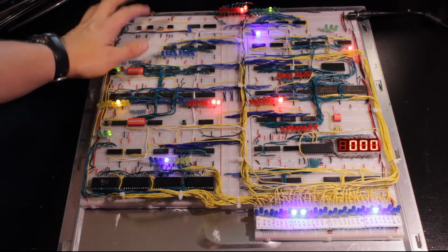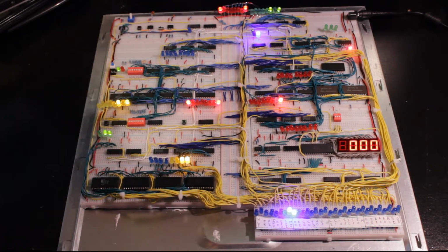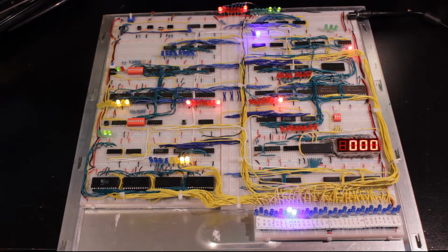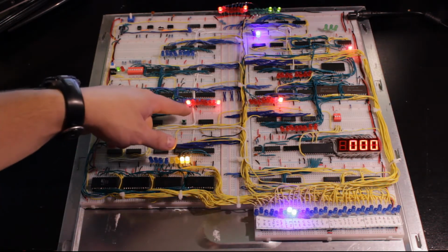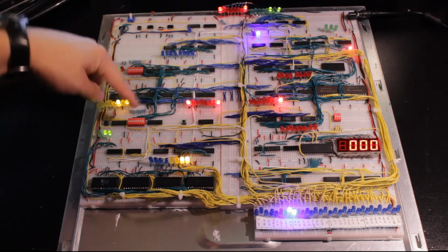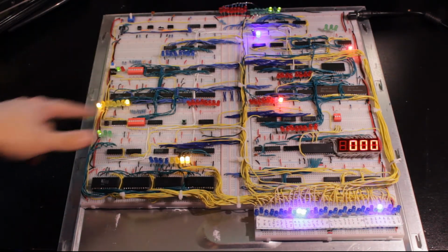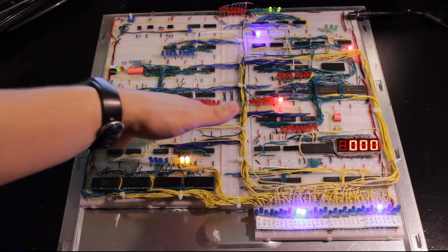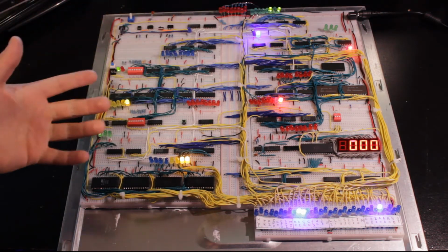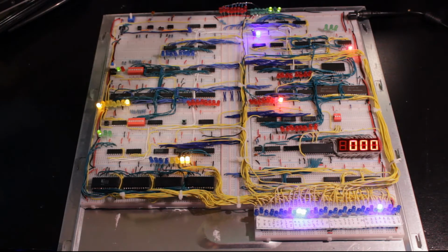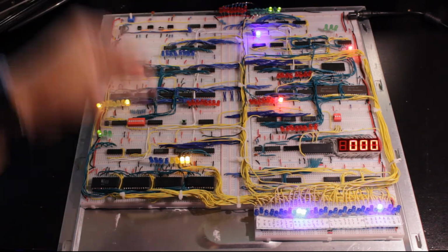which, as we said previously, is going to get a pointer to the location in memory where it's going to store the value held in the A register. So we get that pointer, 0x81, and we're going to take this out into the bus back in the memory address register. Now we're looking at the location in memory 0x81 where we can see we have a value of 0 from the A register. Remember how I said that that executes on that clock cycle, not when I press the button after the fact.